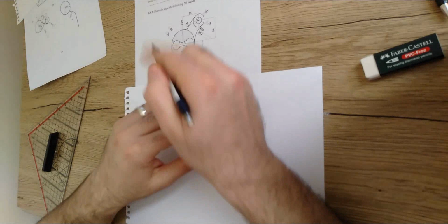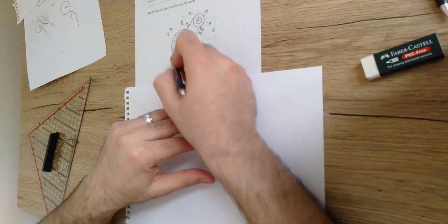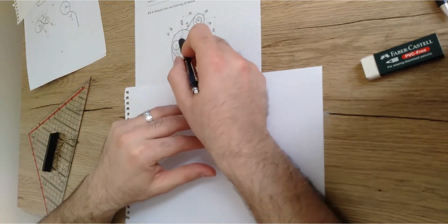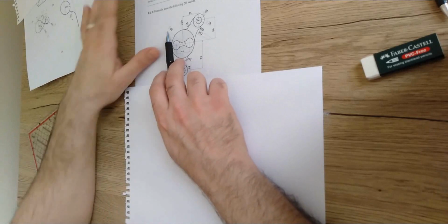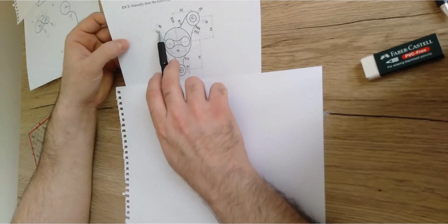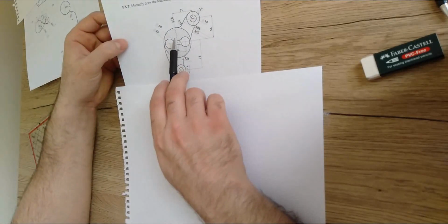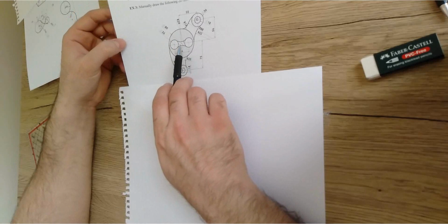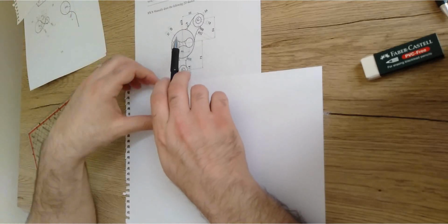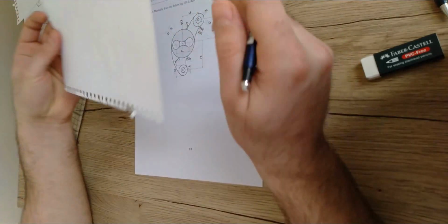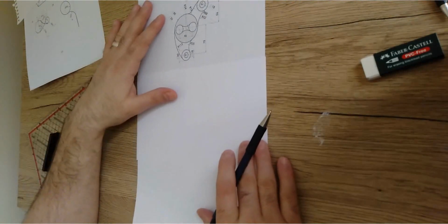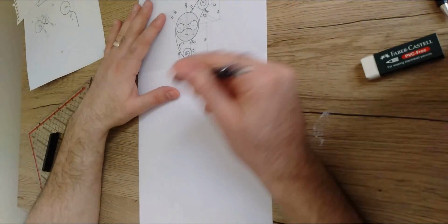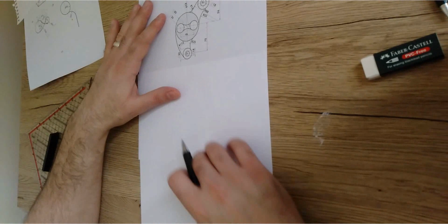Make sense? So in the beginning I'm just going to draw this big circle, and this big circle has a diameter of phi 80. Phi 80 is already defined for this big circle. It means that it has a radius of 40. So in the beginning, from a center point, it is advised, in case you have a drawing sheet, to work in the portrait style. It means in the vertical direction,